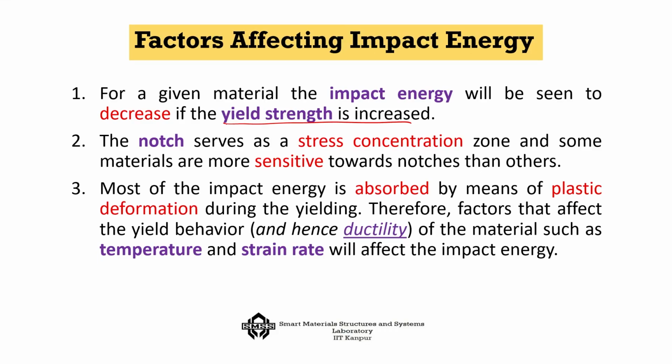The notch serves as a stress concentration. So, whenever you have a notch, that reminds you that that is the area where it will be most sensitive in terms of failure, and most of the energy is absorbed by means of plastic deformation. And that is why factors that affect the yield behavior, like ductility of the material, temperature, and strain rate, they all play an important role in terms of the impact energy.